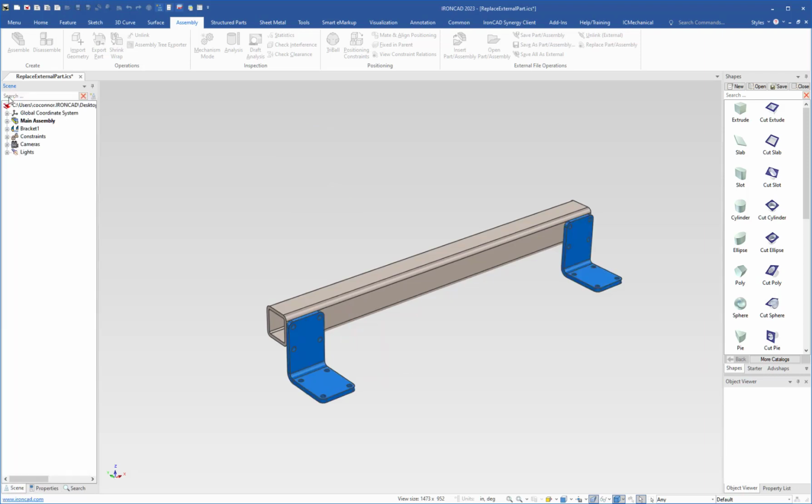And go ahead and start the process and accept our constraints. And we can see that all these files are now replaced within this file. So a very handy tool to replace elements that have constraints that are on external link parts or assemblies within your files.